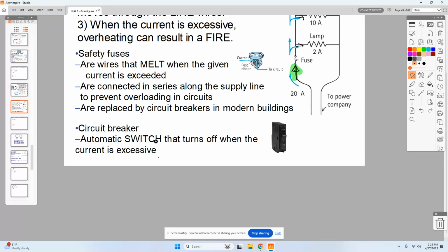Now, once they trip, they're going to open, they're going to stay open, but then you can manually reset it. If you reset it and the wires haven't come back together, it's just going to go right back open, right? That's just because of the way that they've been designed. Now some of them are more electronic than that, but they used to be just a bimetallic plate.